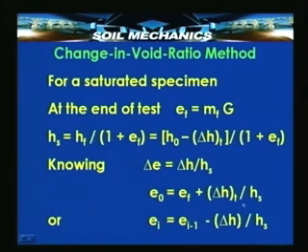So, this is the way we can successively compute the void ratio at any stage from the previous void ratio, knowing the change in height and the height of solids which we determined previously.